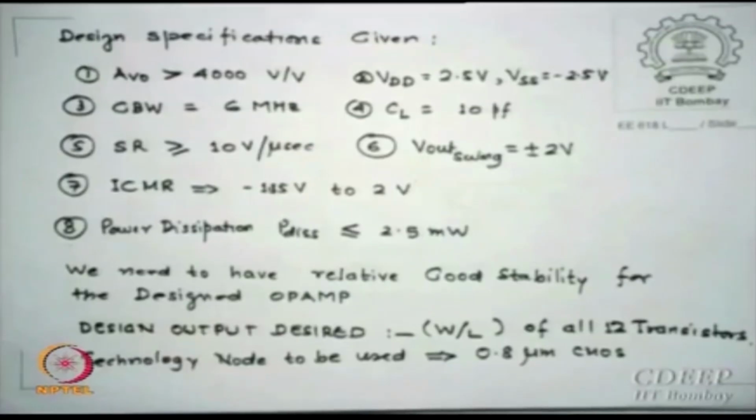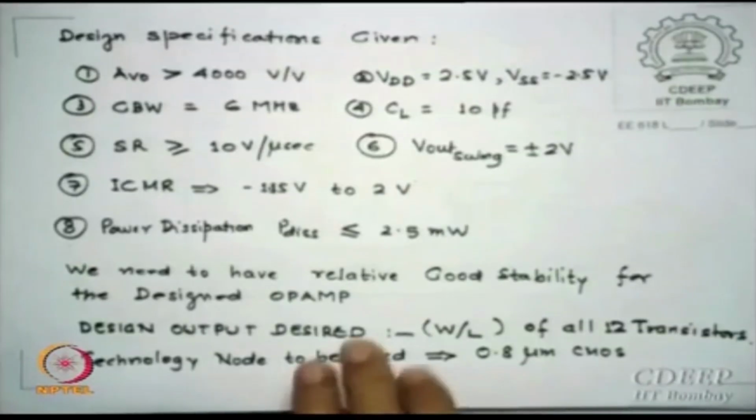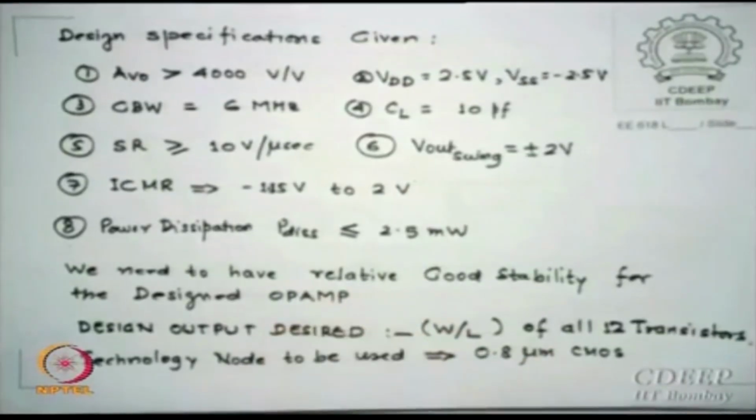Okay. Another worry which we have been talking about this morning is whether the OPAMP design has good stability, and that we must verify. Essentially what does this mean? What phase margin I choose for relatively good stability. So that is my design spec, I am deciding what phase margin I should use.